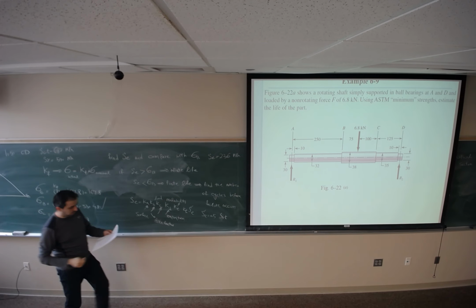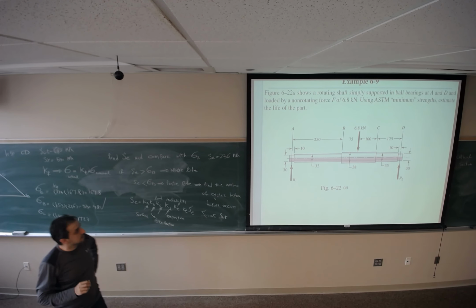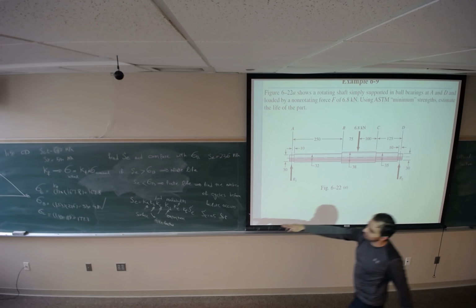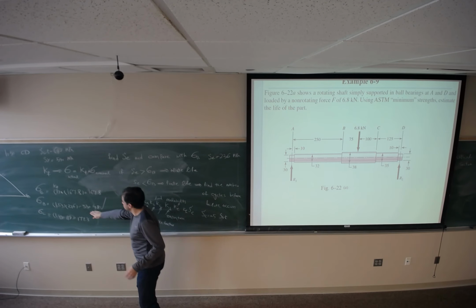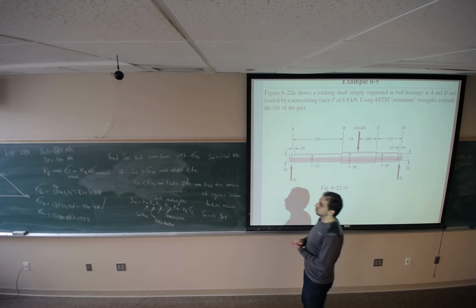This was the last thing that we derived on, I guess, Monday's class. So the endurance limit for this component made of this material is 236 megapascal. Compared with the stress that we have, 330, 236 is less than 330, so we have finite life.